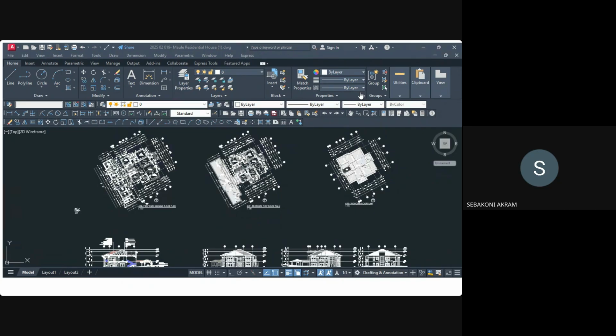Electrical designs, as I've said, first of all, to do electrical designs, we need to first know the load. As we know, what are the components of an electrical system? It's the source, not the generation, but the source of the electrical power. We have the supply system, which are the cables or the lines, and we also have the load. So we first base from the load.